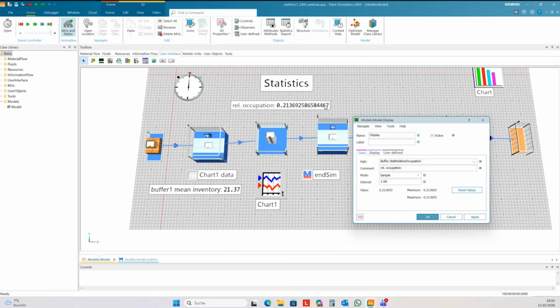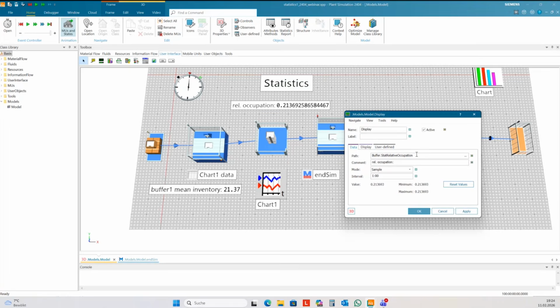Okay, and now I have a lot of digits here, and it's like programming. You can program here in this path field, and you can round, for instance, the value. And now I have a round value. You can also make more complex commands or statements here in this path field. If you can add something, you can calculate here.